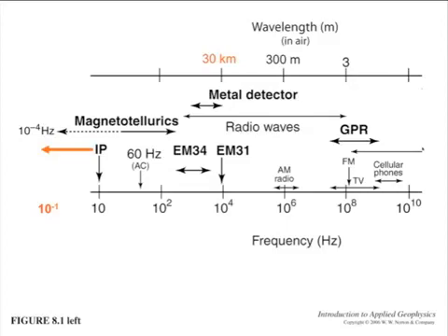Remember, even though our mini res ground resistivity unit has an actual operating frequency of 5 hertz, that's only to avoid setting up too much battery effect, too much movement of ions in the ground. It's an essentially direct current technique. Now, direct current means the current is flowing in the same direction all the time. What comes out of a battery.